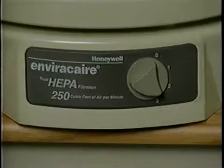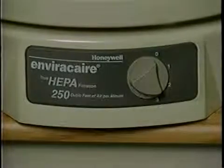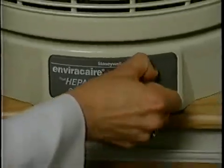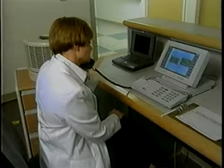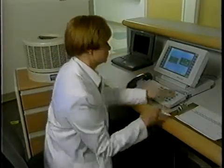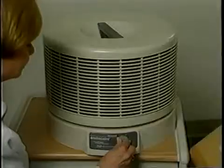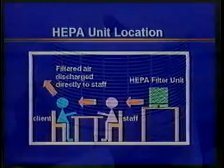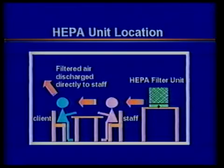Also, they may produce less air than the nameplate lists. We recommend that you size them to produce about 25% more capacity than you want. Also, these units can be noisy, especially at the high fan setting. We recommend that you select them based on the airflow at low or medium speed. Locate the units at an elevation which allows air to be discharged from the unit to the staff at approximately head or breathing level. The discharge can be determined by moving your hand around the unit until you feel the air. When properly located, the staff should feel gentle air movement.